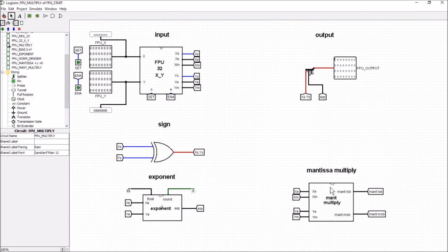So what we want to do is go ahead and test it and see whether we actually get the right values out here for the least significant bits and the most significant bits. So let me change the circuit to do that. We really just want to look at the two output points here. So we can put a probe in, facing south, and we can put the value in.